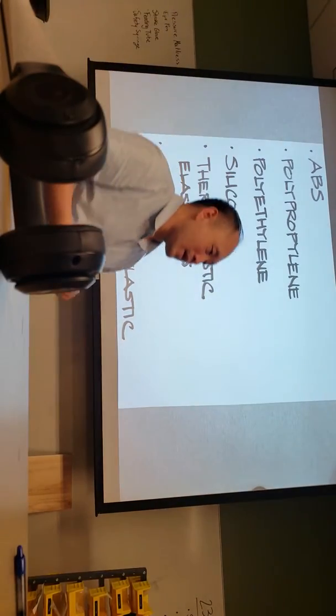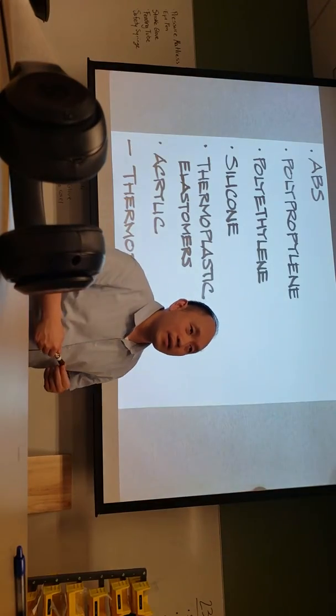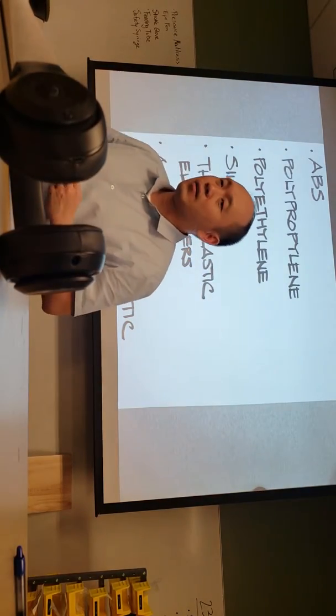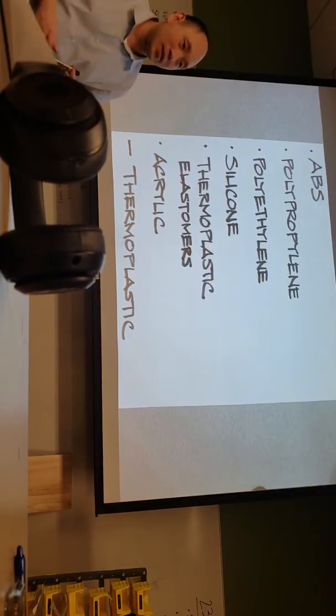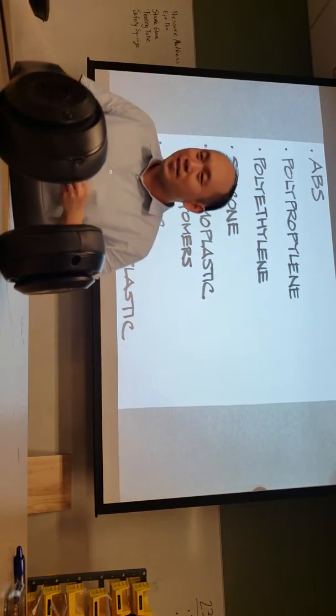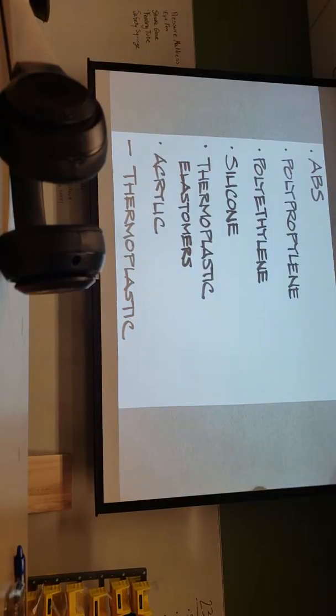So this is a very common plastic because it is very impact resistant, and it doesn't shatter very easily. One of its hallmarks is that it is typically shiny. And if you've ever looked at plastic that's shiny, and if you tried to rub a groove in the surface with your fingernail and weren't able to leave a mark, typically that's ABS. That's one of the ways you can see, the fingernail test, I call it. So ABS is very common, especially for high impact applications.